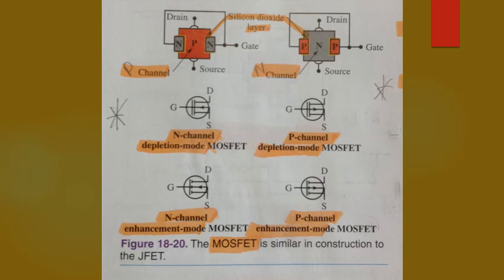The thin layer of high resistance insulation prevents electron flow between the gate and the channel material. The high resistance between the gate and the channel area makes for a very high impedance input device. A high impedance input device is very desirable in circuits such as amplifiers. Also, the channel consisting of the same materials from the source to the drain provides a very low impedance path. A low impedance or low resistance path through the channel is also very desirable for devices such as amplifiers.